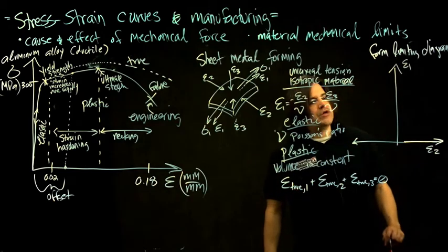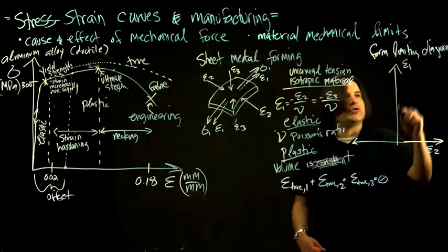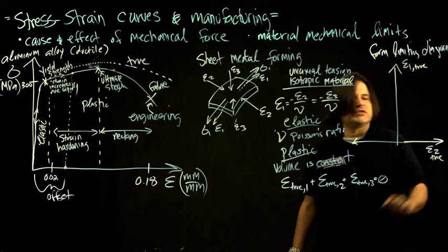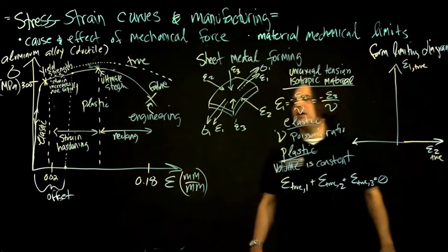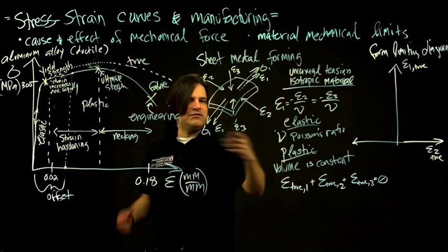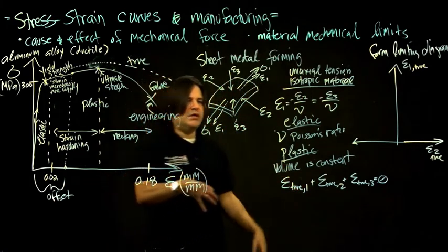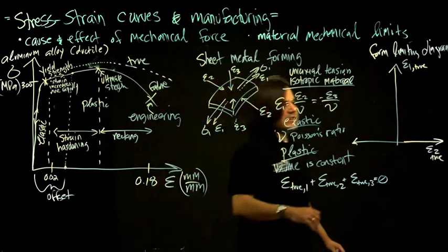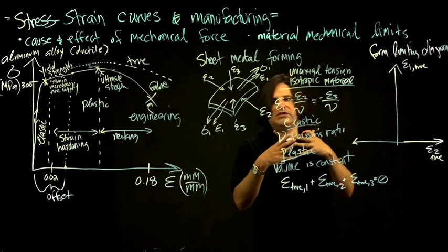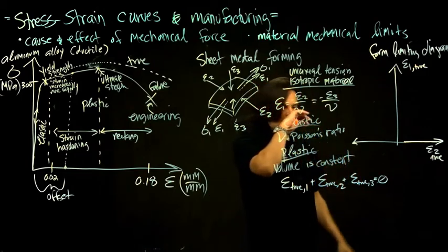And what you do, this is true. This only works for true stresses and strains, one that keeps into account this change in area, because that's the one that is the fundamental relationship between the stresses and strains. The engineering is convenient, but it doesn't describe the general physics of what's going on.